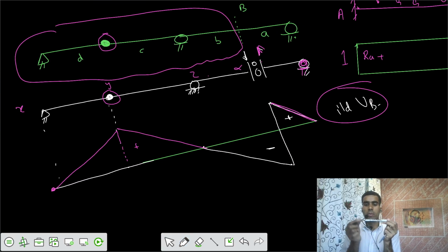So you are applying shear here, you have a support here, you have an internal hinge here. Once you apply a shear of V here, that means this part goes upwards, but because of the internal hinge, it can allow rotation. Once it can allow rotation, there is a possibility that they can rotate, ensuring that the supports are at the same level. So this was the profile. Finally, this was the profile.